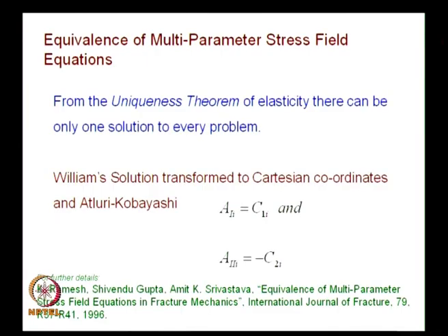All this show that we are converging into an understanding that multi-parameter stress field equations are a necessity. Though the origin of these approaches are different, they converge to a unique solution. We will also see that. So, what you will have to keep in mind is, from the uniqueness theorem of elasticity, there can be only one solution to every problem. This you have to appreciate, and this is very important.